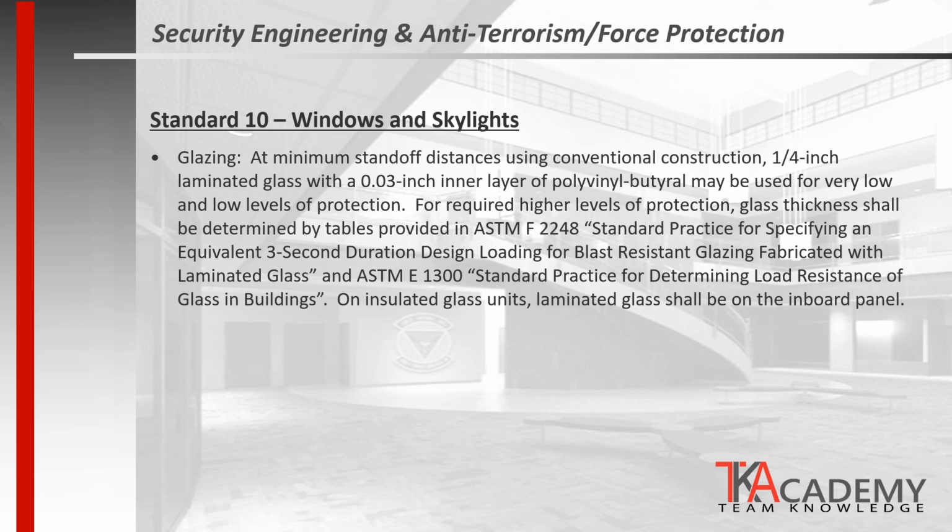When the minimum standoff distances are being met and the facility is using conventional construction, the glazing must be a 1/4-inch laminated glass for very low and low levels of protection. For higher levels of protection, the glass thickness must be determined by ASTM F2248, which is the standard practice for specifying an equivalent 3-second duration design load for blast-resistant glazing fabricated with laminated glass, and ASTM E1300, which is the standard practice for determining load resistance of glass and buildings. Typically, on low or very low levels of protection, the 1/4 inch laminated glass will be sufficient.